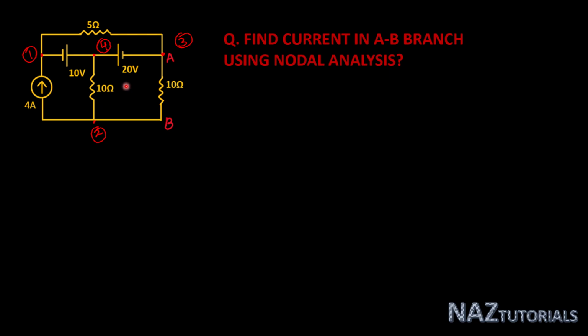There is one more option: you can select node 4 as the reference node. It will give the simplest solution, because node 1 and node 3 voltages we can then define directly. So here we will assume node 4 as the reference node.